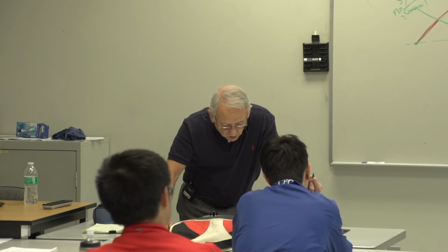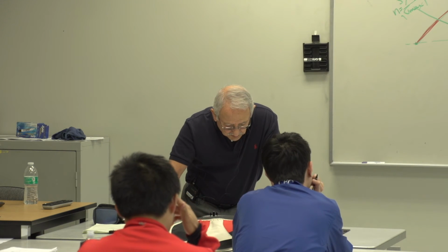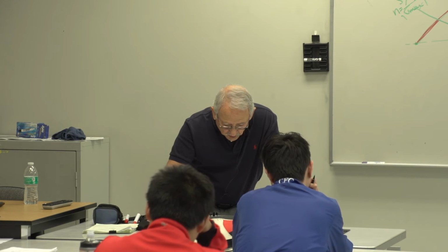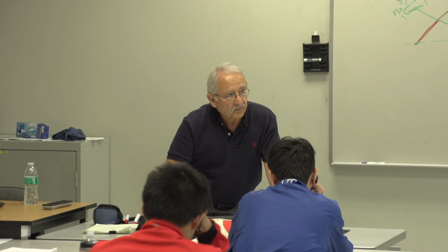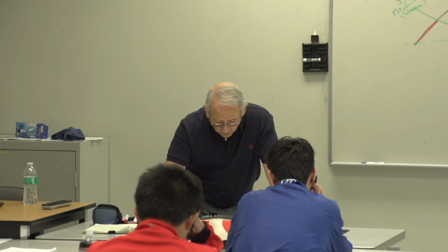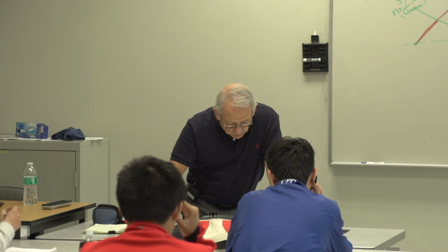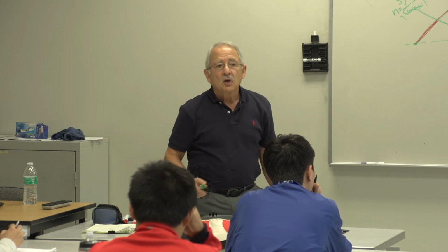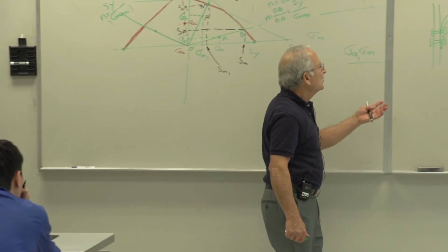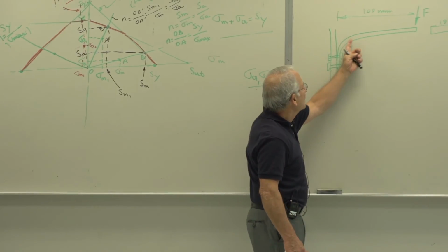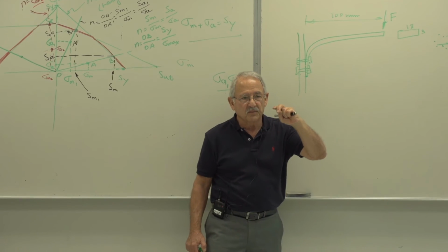The material is ground high carbon steel, bent, then hardened and tempered to a minimum hardness of 490 Brinell. The inner radius of the bend is 4 millimeters. So that's the radius here. And they only give you that because they would expect you to use curved beam equations to find the stresses.